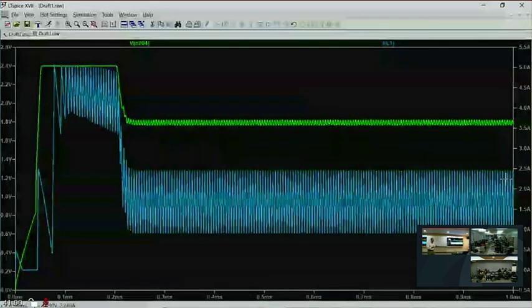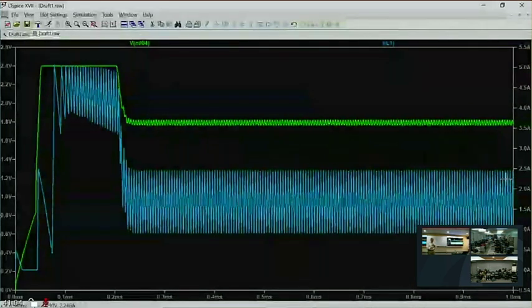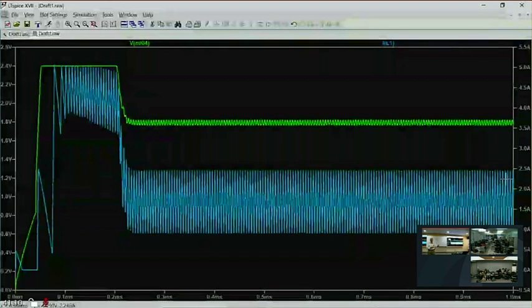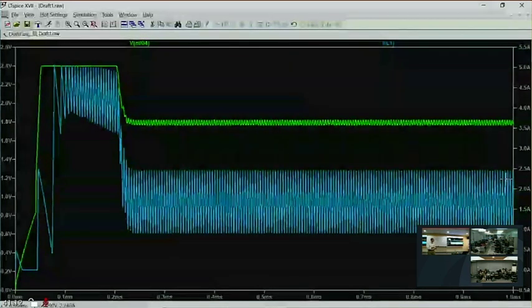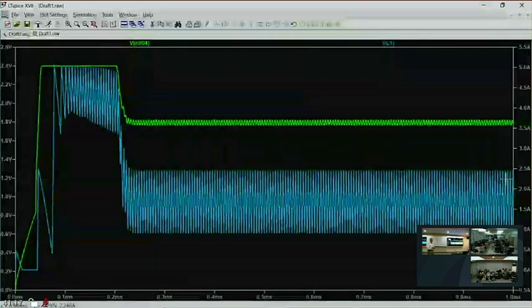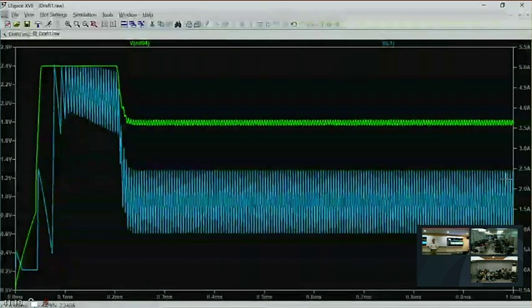See, in AM, the energy in the sidebands is near the carrier frequency. You might encode a kilohertz signal, but you don't have any kilohertz current in the inductor. It's all encoded on the carrier frequency. But in FM, if you have a kilohertz signal in, you can have kilohertz current in that sideband. The sidebands go all the way through the audio frequency spectrum.